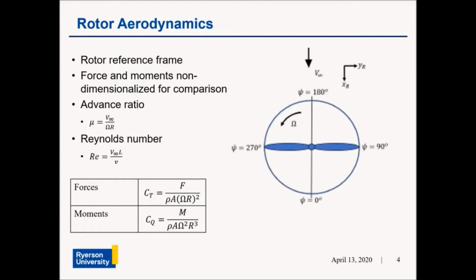Another variable that was used in this thesis was the Reynolds number, which is a ratio of the inertial forces in the fluid to the viscous forces in the fluid, and governs whether the flow is laminar or turbulent. The Reynolds number is used as a similarity parameter for viscosity to scale objects in a flow.